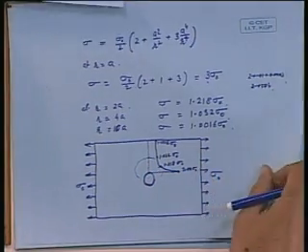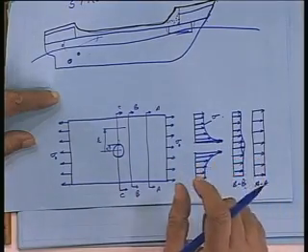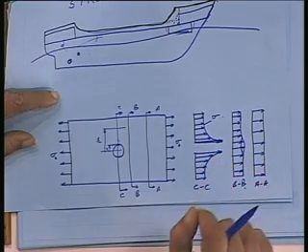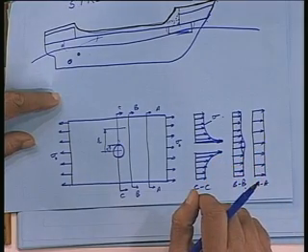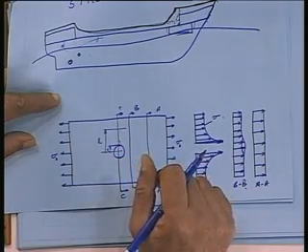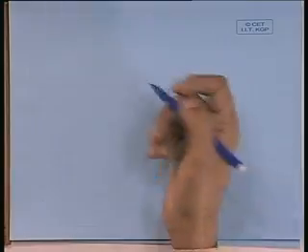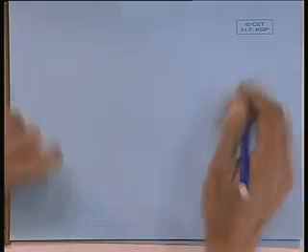So, the concentration of the stresses is around this area. Okay. Now, when we come to the ship's part, this radius we try to put that, one can see that more will be the radius here. Again, from elasticity you will find that this stress which is here will get slightly tapered down. Okay. So, if you are having a smaller hole, more concentration will be there. If you have a bigger hole, then the concentration is reduced.